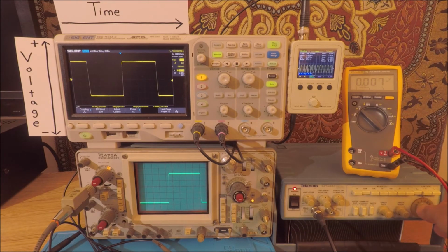Now, if I were to start reducing the frequency, notice that our square wave, now we're at a trapezoidal wave, so we're in transition back to a square wave, starts to reappear on the small scope, and now we get a nice square wave back again. So somewhere around here, we're starting to hit the bandwidth of the portable oscilloscope. That's around 44 kilohertz.